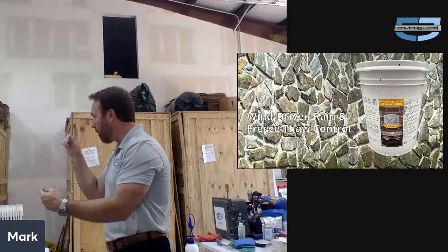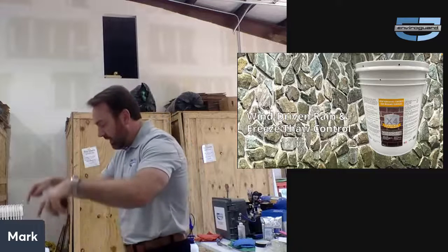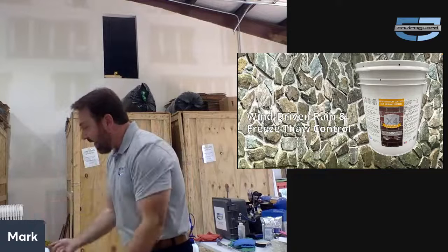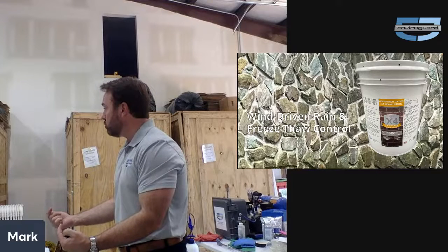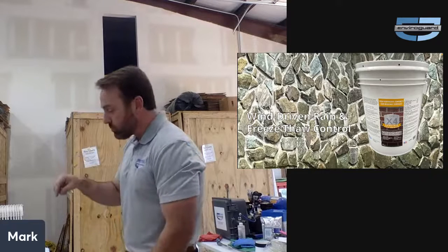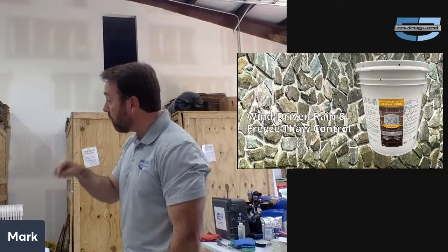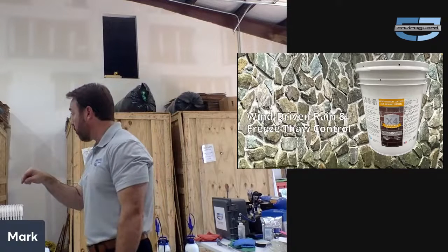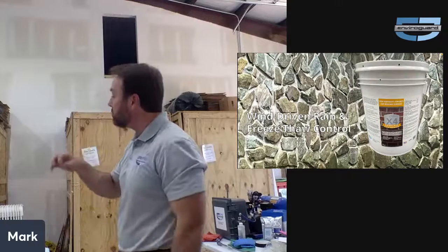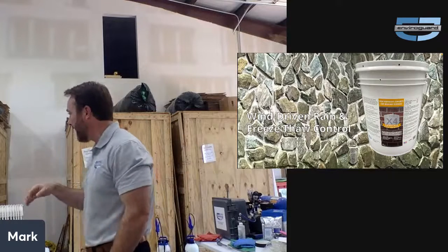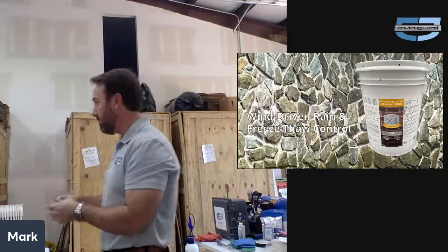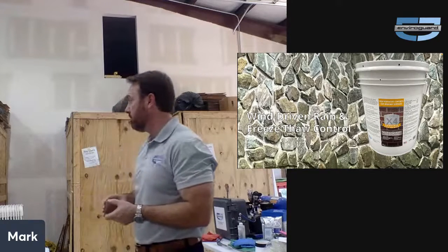So there's one problem. But the other problem is that as moisture was accumulating in the soil, water was coming up through all of those expansion joints as well. What we did was we took a 1-part moisture cure resin and we filled all those up, right? And it expands, and the moisture within that is what cures it. Then for 24 hours, we ran water around just to make sure nothing came back up. Something like that could work really well.